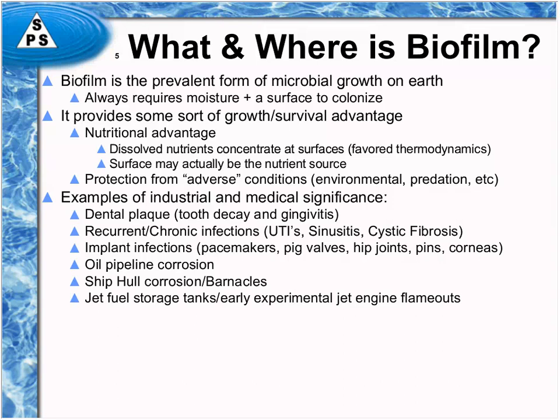Jet fuel tanks in the early days of the experimental jets were the cause of biofilm growth because they weren't necessarily rain tight, and water would leak into the storage tanks, and then biofilm would grow at the water fuel interface. These mats of biofilm would get sucked out and put into jet engine fuel compartments, and when this hunk of biofilm got picked up by the fuel line, it would clog the orifices in the jet engine, and the jet would crash because the engine would flame out.